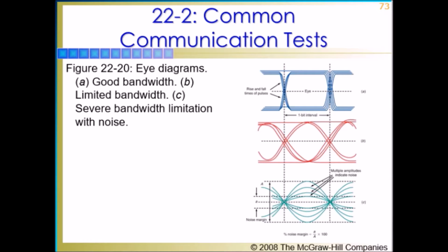The longer the cable and the higher the bit rate, the greater is the distortion. The pulses tend to blur into one another, causing what is called intersymbol interference. Intersymbol interference makes the voltage levels for binary 1 and 0 closer together, one bit smearing or overlapping into the other.